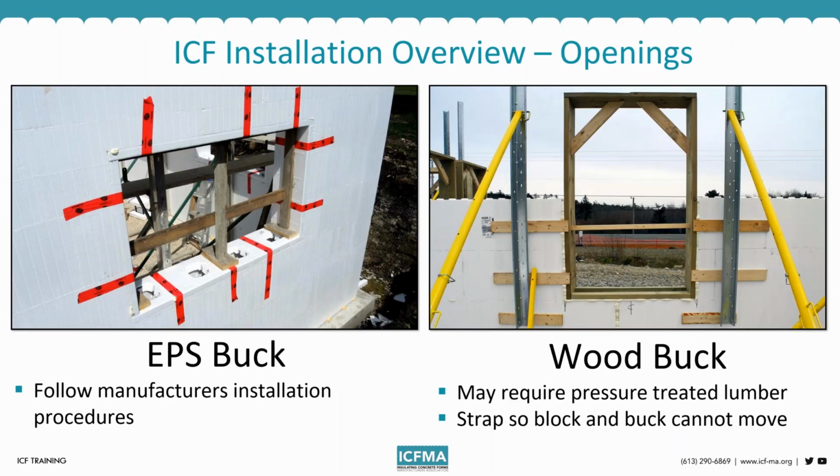There are also several different ways to finish out your doors and openings. This is a very common question about the system. Many manufacturers have EPS buck systems, so they actually have a foam product to finish off their walls. Or it's very common to use wood bucking in most situations to frame out your doors and windows.